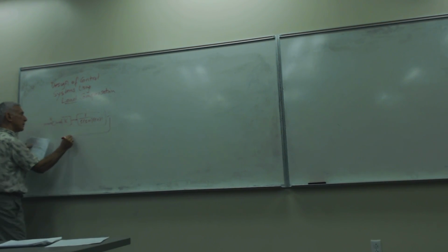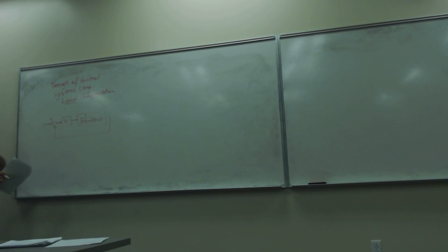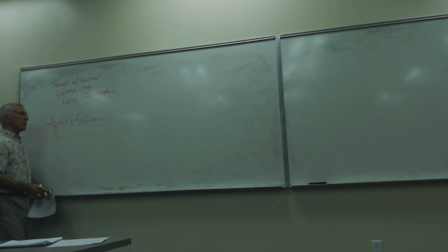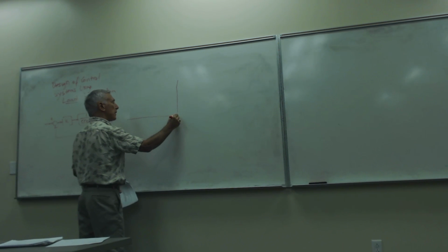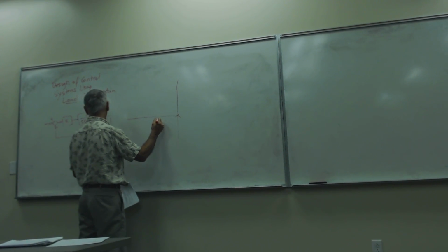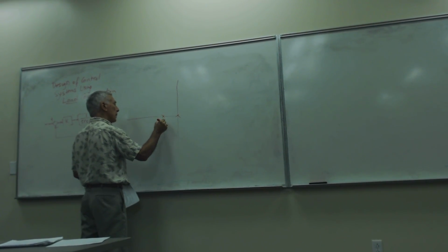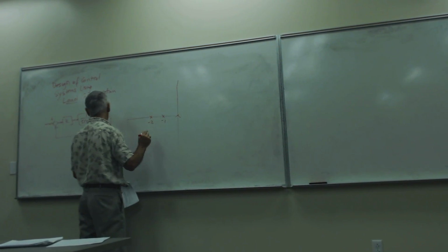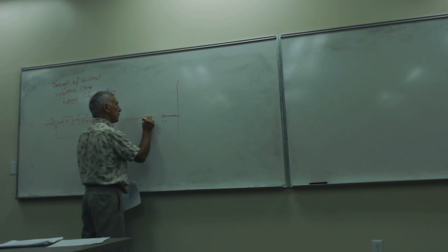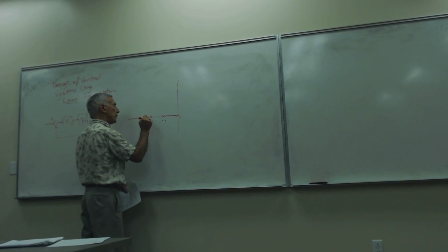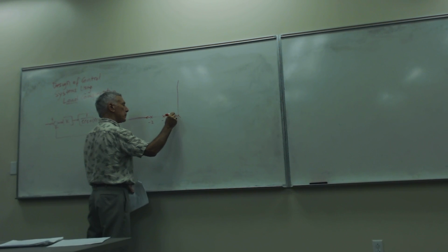And so we can draw the root locus for this as the gain K increases from 0 to infinity. What we do is put down all the poles. We have a pole at -1 and another one at -2. And so we know the root locus will exist here, it will move in that direction, in that direction, in that direction, and it will break away somewhere.